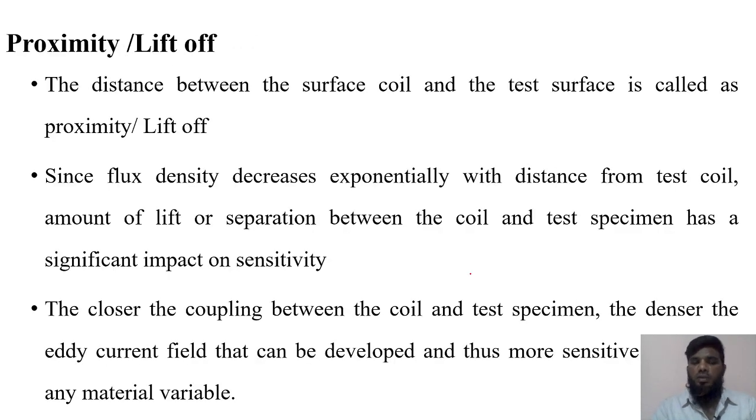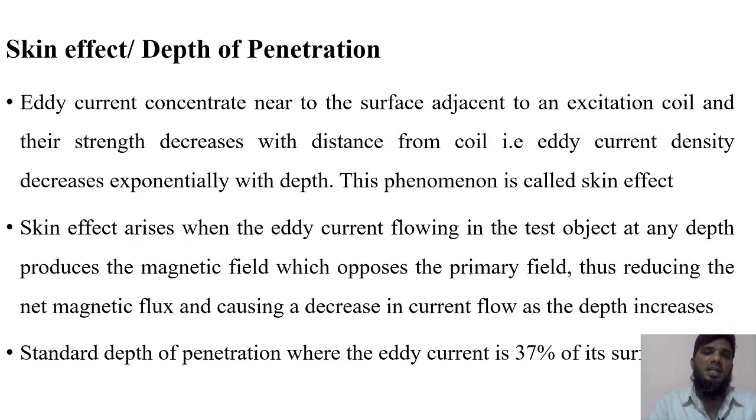Okay, so if you bring it too close, the induced current will go deeper into the surface. If you are not bringing it closer, if you are keeping it lifted, the eddy current will be generated only on the outer surface of the specimen. Because of that, you cannot study the defects inside the surface.